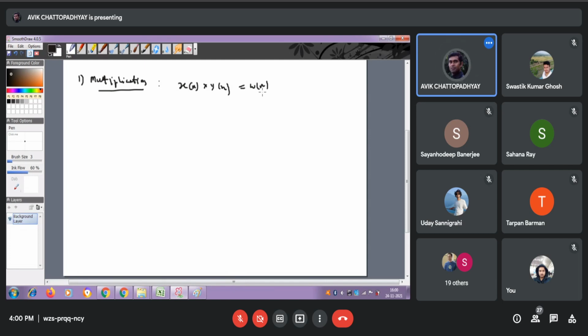Now, while multiplying the corresponding samples, if you don't have any particular value, meaning a non-zero value for that particular sample, you just put a 0 there. It is called plugging in the value 0. If there is no sample, or if it is 0, then it is okay. If there is no sample, you can put the 0 value. This is called zero padding, or zero adding.